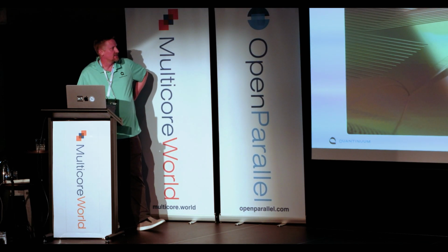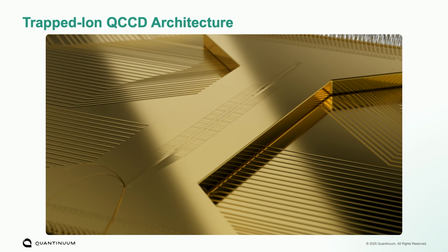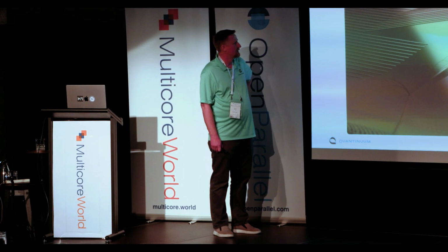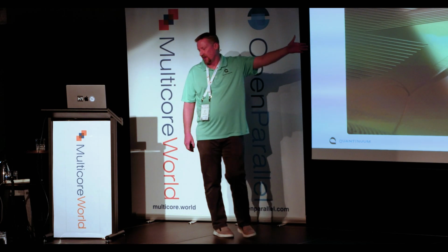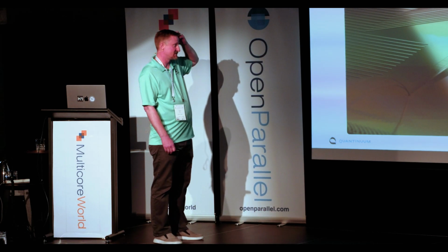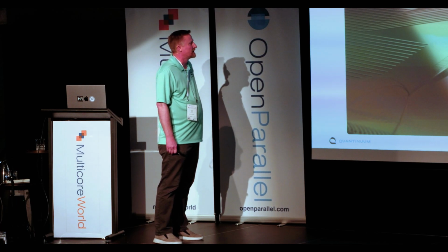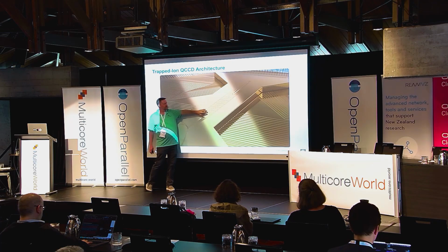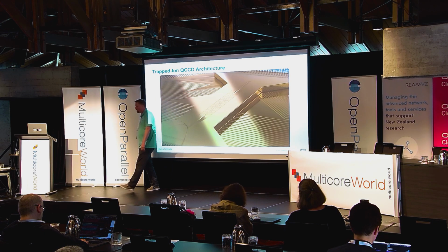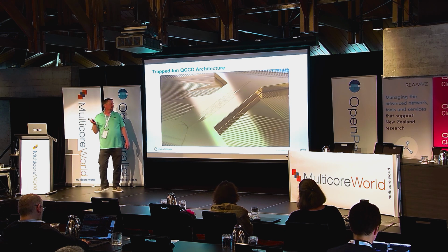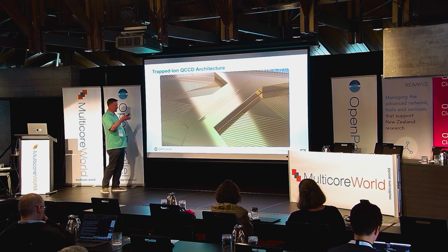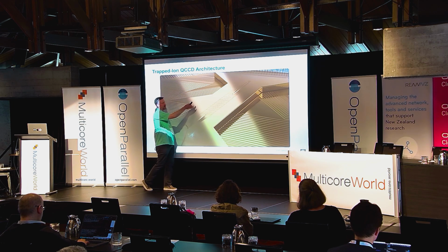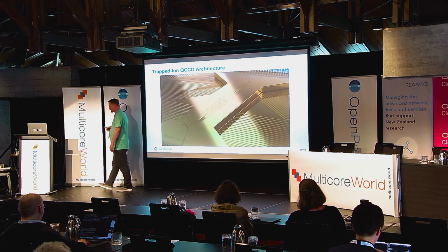So Chris showed a similar picture. I think these are very beautiful ion traps. This is a 3D rendering, but we have some very nice photos as well. As you mentioned, this is in silicon. This is CMOS. This was made up in Plymouth, Minnesota, at the Honeywell fabrication facility. But it's CMOS that's only passive at this point. These boxes are just little electrodes. They have multi-layer metal underneath to route electrical signals, and you're just putting electrical signals on these electrodes to trap the ions in 3 dimensions above the surface of the trap.